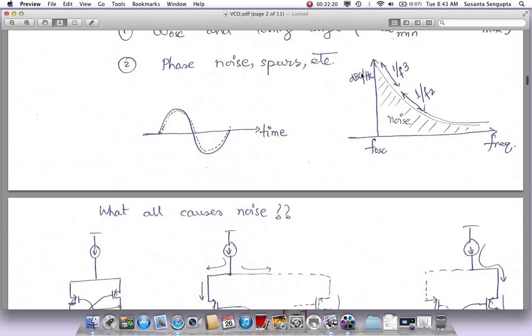So you have to see, if your carrier is, let's say, 1 volt swing, and you integrated everything to be, say, 80 dB, that means 1 volt divided by 80 dB, which is how much? 100 microvolt, right? Yeah, so the integrated noise in 1 megahertz will be 100 microvolt. That is how much will come from the active circuitry, which is causing the oscillations but also adding noise, and maybe from other sources, we'll look at it later.